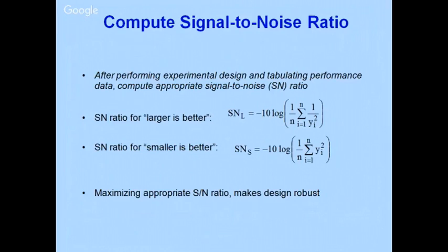What difference it is ultimately going to make is that though the response characteristic is seeking the minimum value, you remember for the second one, surface roughness, we had taken the minimum the better, so my response characteristic is seeking the minimum value, but my SN ratio will still seek the highest value because of this change in formula. So my SN ratio will always seek the highest value. That means I am suppressing the noise and maximizing the effect of controllable factors. That is what I mean by SN ratio.